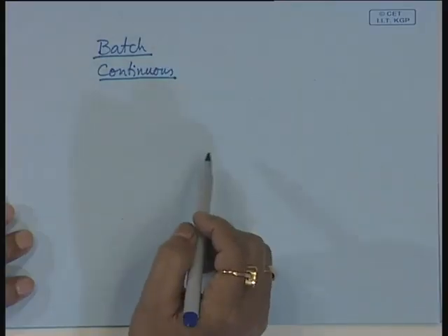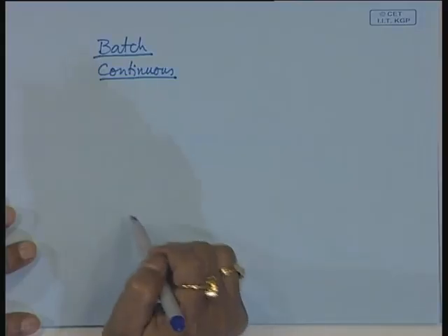So it is carried out up to lower conversion, and then there needs to be a provision for recycling, separation, isolation and purification of the unreacted ingredients, and those isolated, separated and purified unreacted ingredients need to be recycled to the reactor. Again, in a batch reactor there may be only one vessel which is used for polymer manufacture.